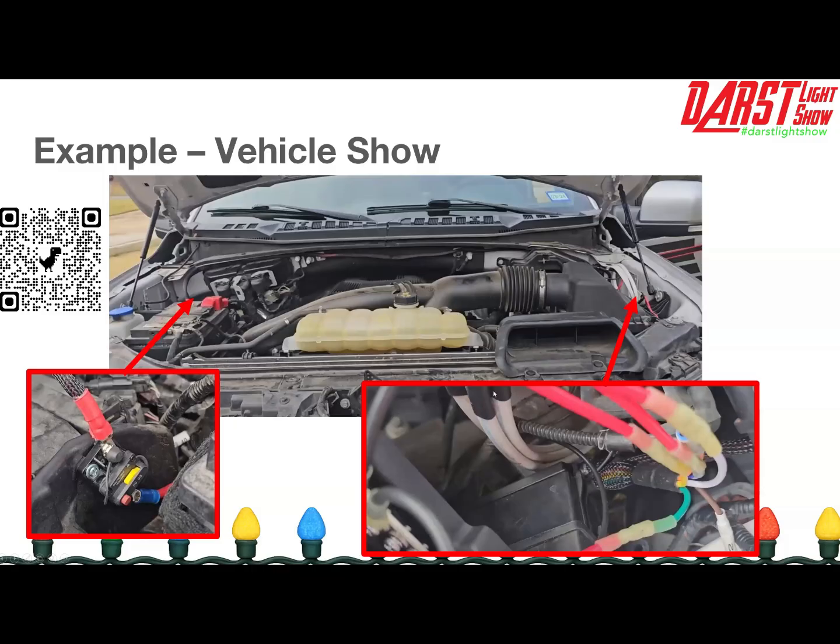And then you can see these white wires. This is marine wiring that I use to distribute power all around my truck. I used a 10 gauge marine wire, or maybe it's 10 or 12 gauge, distributed off of each of the different outputs of the relay box. That comes up under here and then goes under the truck. One of them runs over here to the grill, and the others all run to the bed of the truck.